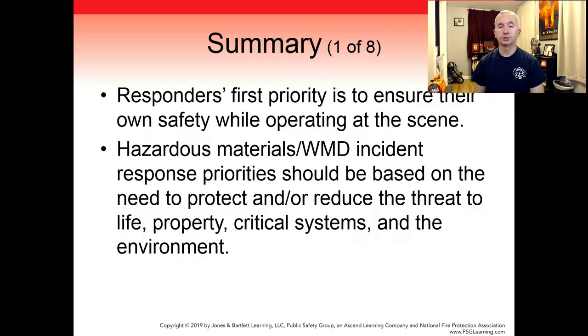The type of PPE required for the incident depends on the material involved and any specific hazards, the physical state of the material, and the tasks being performed by the operations level responder. The selection and use of chemical protective clothing may be the greatest direct effect on responder health and safety. The EPA defines 4 levels of PPE: Level A, which is the highest level, Level B, Level C, and Level D, which is the lowest level.